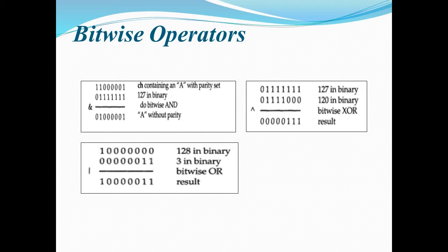Now the second example that I have taken is for the XOR gate. Here you can see that whenever the bits are different, the output is 1, and when we have similar bits, the output is 0. Let us go with D0. Here it is 1 and 0, so the output is 1. The next combination, in D1, is also 1 and 0, so the output is 1. Whenever we have similar bits, let us take the D4 position, it is 1 and 1, so the output is 0. So whenever the bits are different, the output is 1. When the bits are the same, the output is 0. Here the only change is that instead of instructions we are using some symbols.